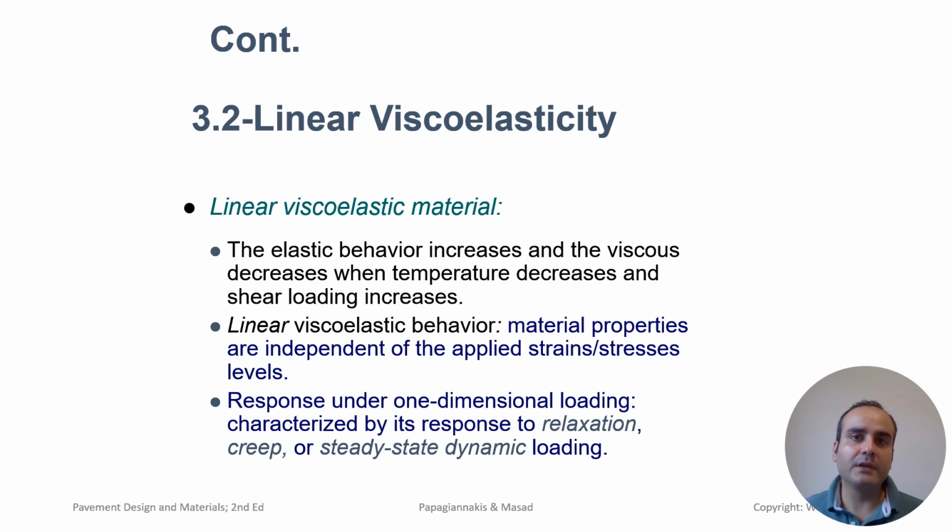The shear strain behavior of asphalt binders is important for understanding how asphalt reacts under the stresses imposed by traffic loads and environmental conditions. Asphalt binders, as viscoelastic materials, exhibit both elastic and viscous characteristics depending on the applied load and temperatures. Shear strain in asphalt binder is the deformation that occurs when a shear force, which is a force applied tangentially or parallel to the surface, is applied to the asphalt binder.